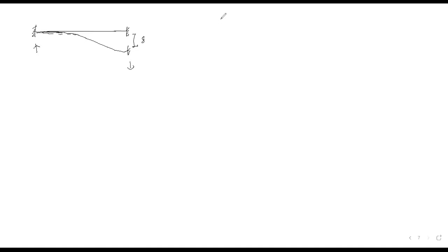For that, we have to provide anti-clockwise moments at the ends. Yes or no? इतना clear है? For such a condition, we have the equation 6EI delta by L square. Please confirm me, students. Is it clear or not?